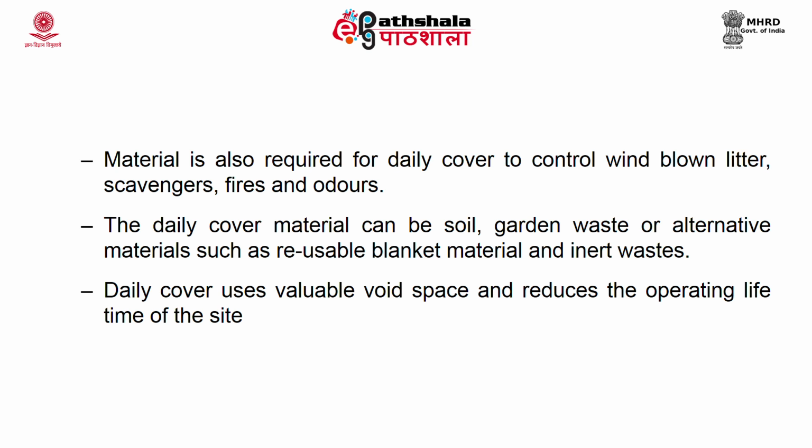The negative side of the daily cover is that every time you spread one layer of cover over the waste material, it will occupy landfill space, thereby reducing the operating time or the design period of the landfill. That means you would have designed the waste loading for a period of 30 years only for the waste that is generated or brought to the disposal site. Now, if you keep covering the waste with a daily cover, it will add on and the lifetime of the landfill will be reduced.